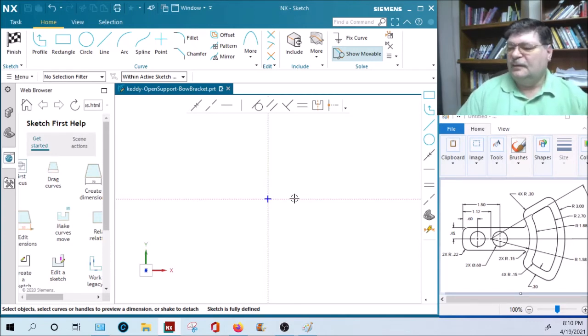Whereas if you have a part in millimeters, if it doesn't say it's metric, look at the numbers. Typically they're increments of 5, 55, 40, 60, 120. They're typically integers though, and not always, but in the book they are. So this is in inches. Make sure you start the part in inches. There's no easy way I know of to convert an NX part into another unit.